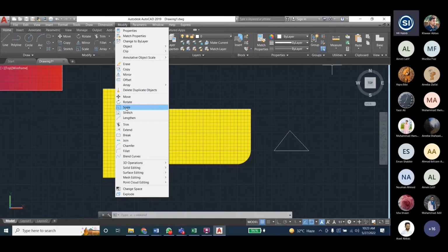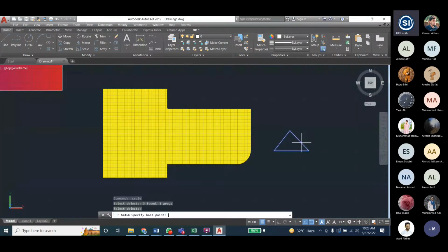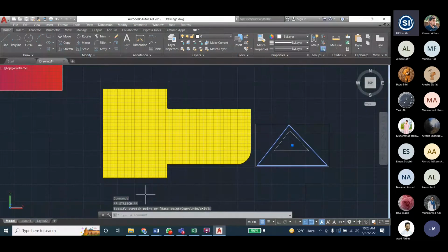If you scale it, maybe double, it will be doubled, but keep the copy. You see here the specify factor copy. You will select it, copy, then specify scale factor 2. You see it is scaled, but you see the center point, the reference point. If you mention the center point, then it will be the reference here. Otherwise, you can change the reference point.